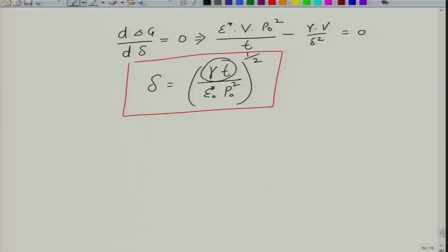So basically these two factors lead to larger delta and these two factors lead to smaller delta. This is the surface energy term, and this is the term which is related to polarization or depolarization energy of the material. So, this is the stable domain size that you get in the material essentially. Now, different types of crystals will give you, how does it look macroscopically?